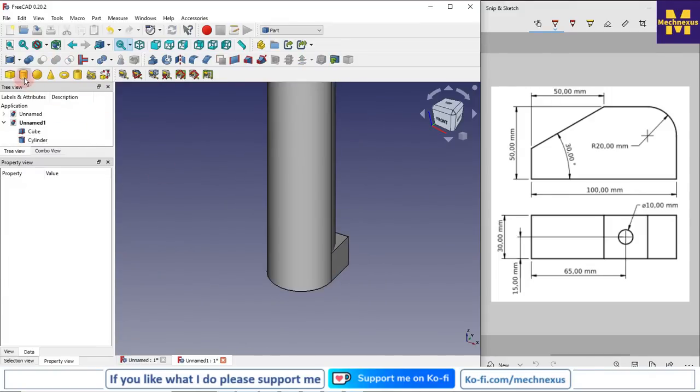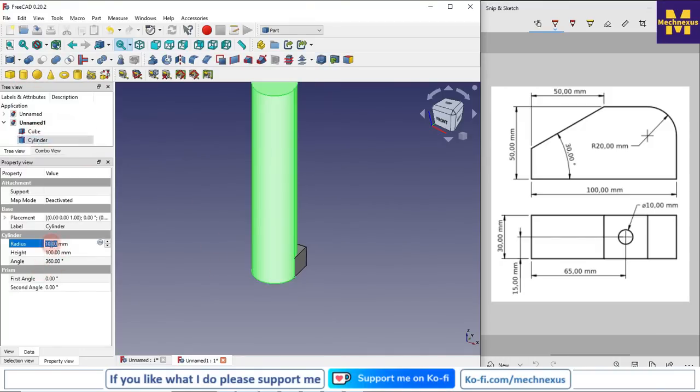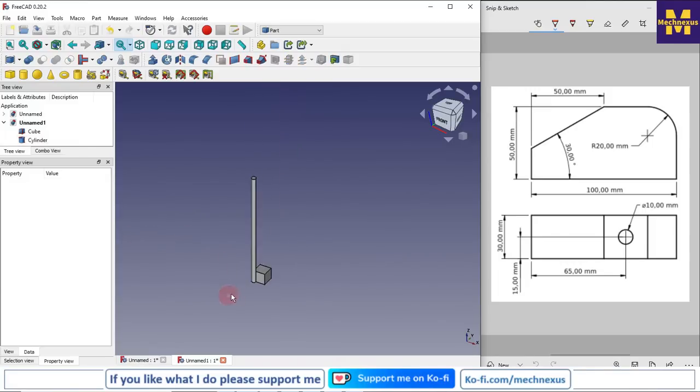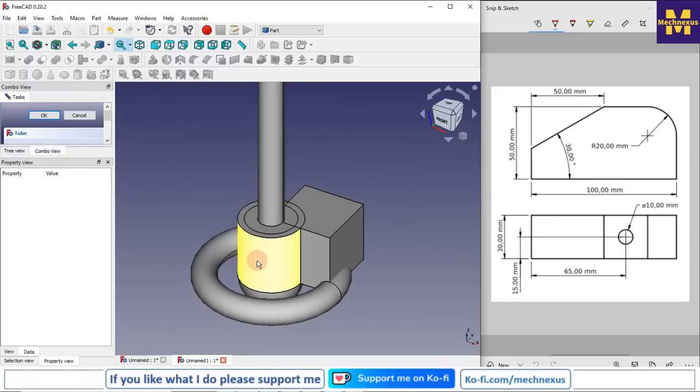So whatever part primitives we insert, we can change any values like length, height, angle with the help of this property view. This way we can insert any shape. So this is how you can insert the standard shapes in your part.